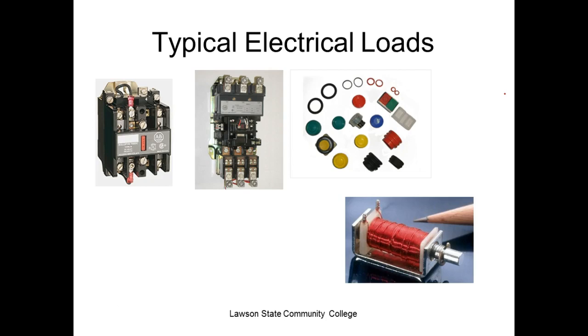A motor is an actuator, but a motor has its own name. Normally, a rotary actuator has a limited motion. It would have mechanical stops, and the arc can only go so far. A motor is an actuator that has no limits. So it would do what? It spins as long as you let it spin. A motor has its own name, even though it is technically an actuator. So your actuators are going to be your loads.